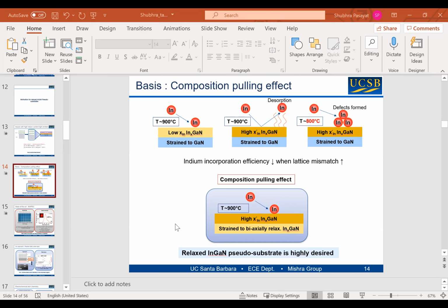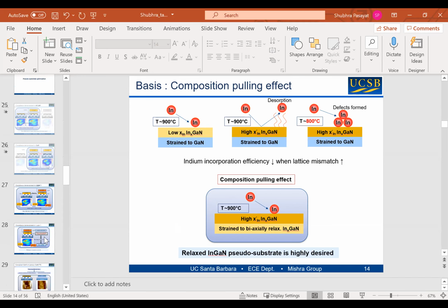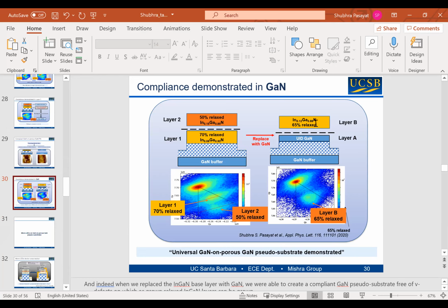Can you go over the effect of using GaN instead of InGaN for the template? So the reason for our GaN still working is because it was, again, very thin. Now this is not our pseudo substrate. The pseudo substrate is the InGaN which is formed above it. So now we are not trying to incorporate more indium.